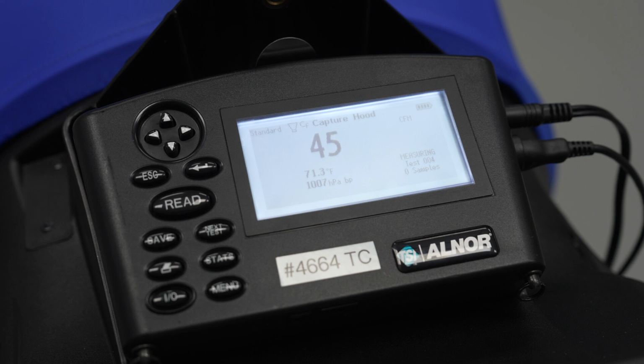The correction factor of our hood should not, and thankfully does not, need to change in this setting. Once we corrected our terminal airflow, it was showing around 47 CFM. Our flow hood is showing 45 to 47 CFM as well. And that's all she wrote.